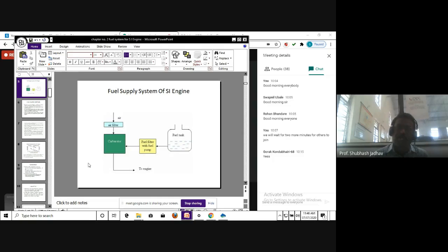Now, what is happening when the droplet is going over there? Every droplet is now surrounded by air, and therefore every droplet is able to take some amount of heat from the air surrounding that particular droplet. So now we have increased the surface area of water by breaking it up into smaller particles. Why have we done this? Because we want to absorb the heat. When we absorb the heat, that surrounding region becomes cooler in this shed net. Similarly, in a carburetor, when we supply the fuel, we break it up into smaller particles.